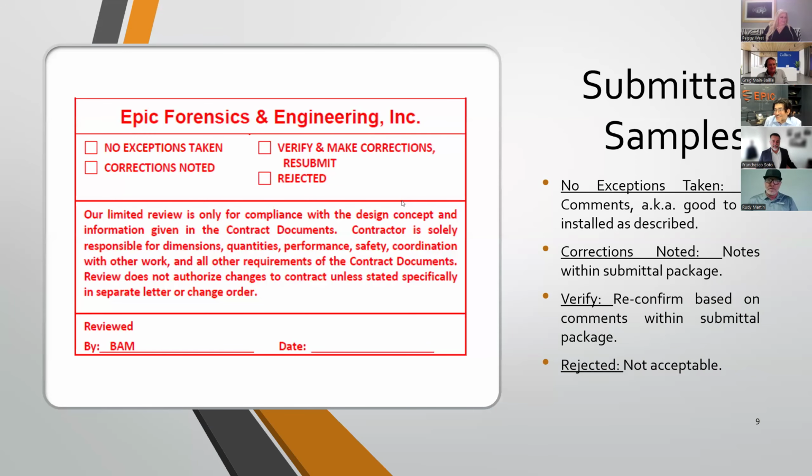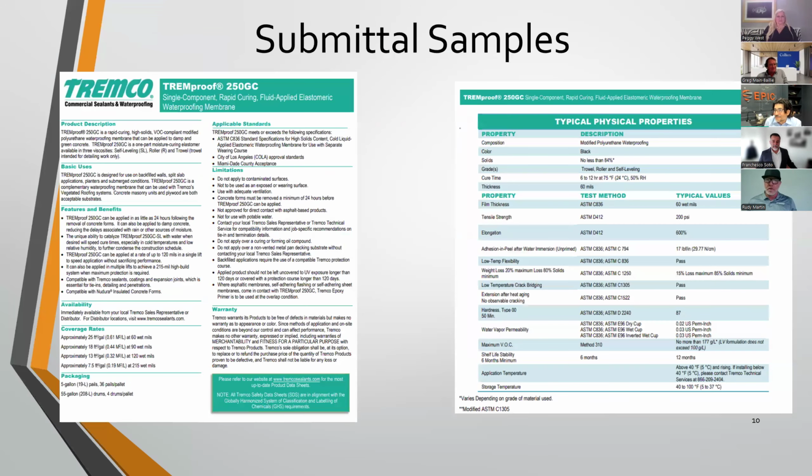Well, sometimes they're just little things, like paint the cooling tower. We can't paint the cooling tower with the same paint we painted the building, and nobody specified that. It was one small thing that was overlooked. So now I have to say, we have an issue. I don't want to be held to a standard from a warranty standpoint when that cooling tower frame fails, because the cooling tower is usually always wet.